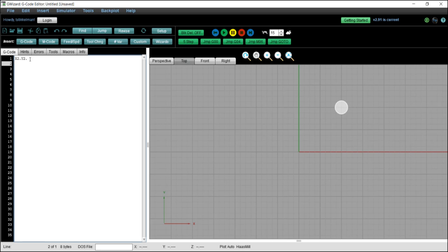So I hit enter and I'm going to have a 4x4 square and I'm going to find the intersection points. So the next one will be still x 2 but y will be -2 inches, and notice it went to that position. So now we'll go to x -2 inches, y -2 inches. Then we go to x -2 inches, y 2 inches. And then we make one more entry to close that square up. We'll go back to x 2 inches, y 2 inches.